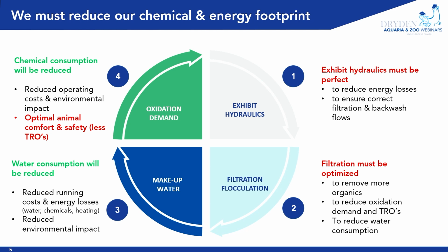The totally closed system virtually doesn't exist. You need to make up for minerals lost. And in any case, you will always lose some water in backwash, and you need to make that up. So also very important. And finally, oxidation demand is governed by the efficiency of your filtration. We would like to make this quarter of this diagram as small as possible.